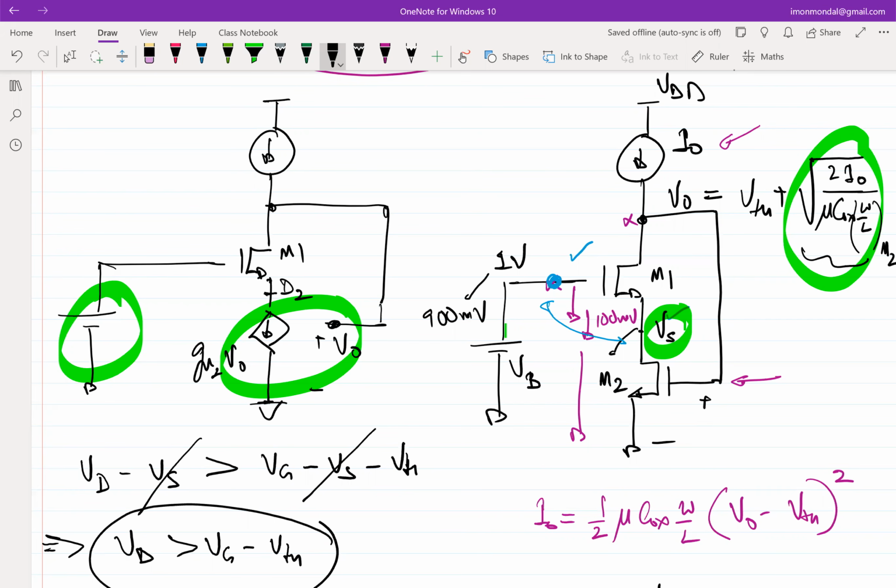So we established that the maximum voltage of VB is 1 volt, and the minimum is 800 millivolt. Well, let's say that I'm not satisfied with that 800 millivolt minimum, for whatever reason, maybe there is a previous stage and whatever the conditions might be. I want to make it 700 millivolt. That is, I want to drop the minimum VB min by another 100 millivolt.